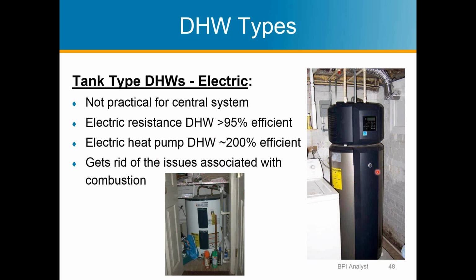And then there's heat pump water heaters, which is what this one is on the right. They operate just like a heat pump does to heating or cooling your home, except it heats the water. They're going to be 200% efficient or better. They do heat water even more slowly. So one of the downsides of a heat pump water heater is usually you need to have a larger tank because it cannot recover as quick when you're taking showers.